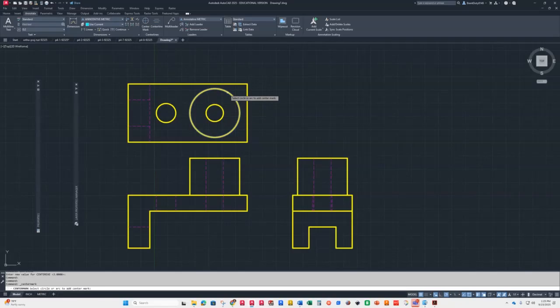For these two, you only need to pick the bigger circle, and then you need to pick that circle. And that's it. Go to center line, and then you pick this line and this line. Hit enter, go back and pick these two. And then just pick these two, and you'll be fine. Like so. That covers both of them.